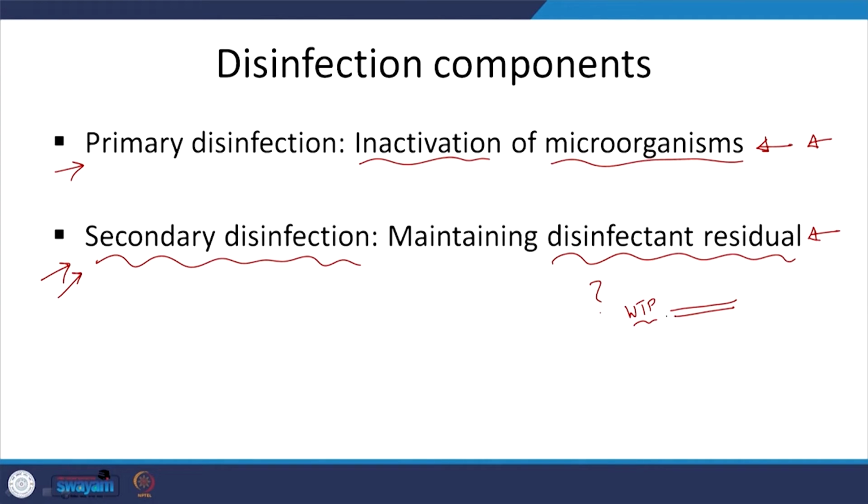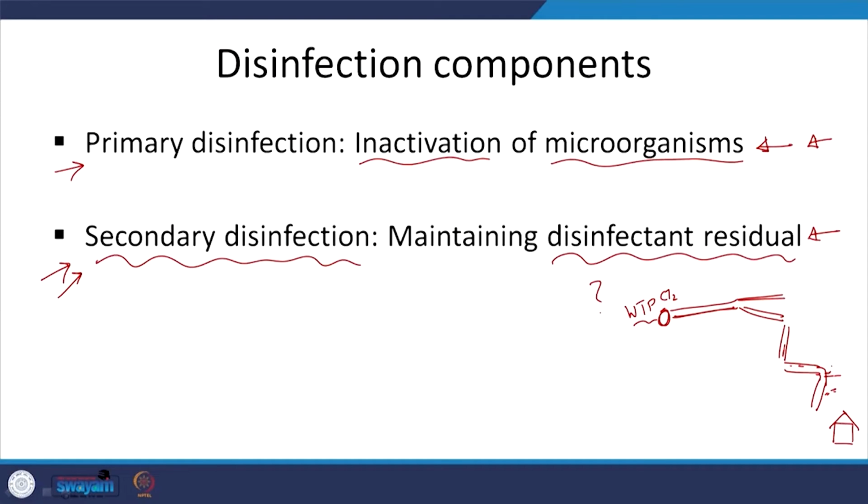So in the context of the water treatment plant, this is not the sewage treatment plant, the water will have to be pumped over long distances to different locations, right? So you can have microbial growth again, though you apply some chlorine here to kill the microbes, because of this long contact, long traveling time. By the time it comes to my home, at least in the Indian case, this is always the case, especially in the joints, I can have sewage from the nearby sewage lines coming in contact with the distribution network, or penetrating the water distribution network, and thus contamination of the water.